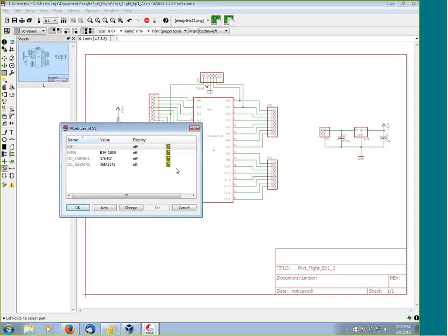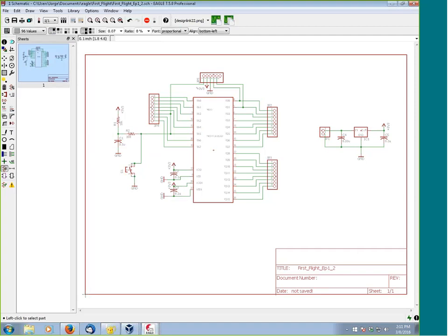Here for the switch, we have all these other attributes. So as you can see, the attributes are user definable. They're very easy to do. You can also add attributes to the whole schematic and then fill in the respective values using the attrib add UOP that's up on our website.